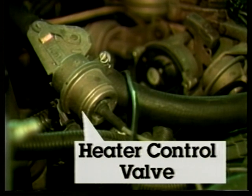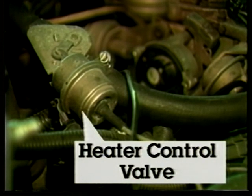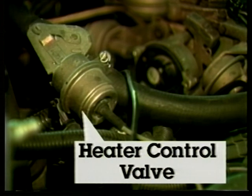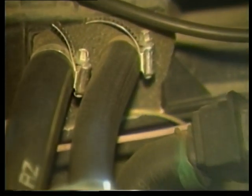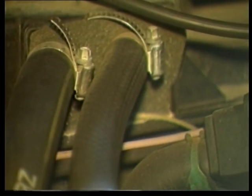It can open or close to control the flow of hot coolant through the heater core. It is vacuum operated. The vacuum diaphragm opens or closes the valve by operating off the supply vacuum provided by the dash control panel. Here you can see how the heater hoses fasten to the heater core.